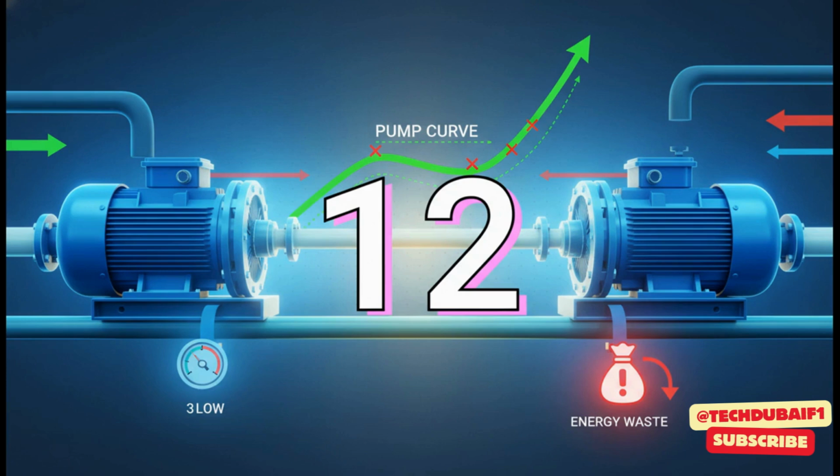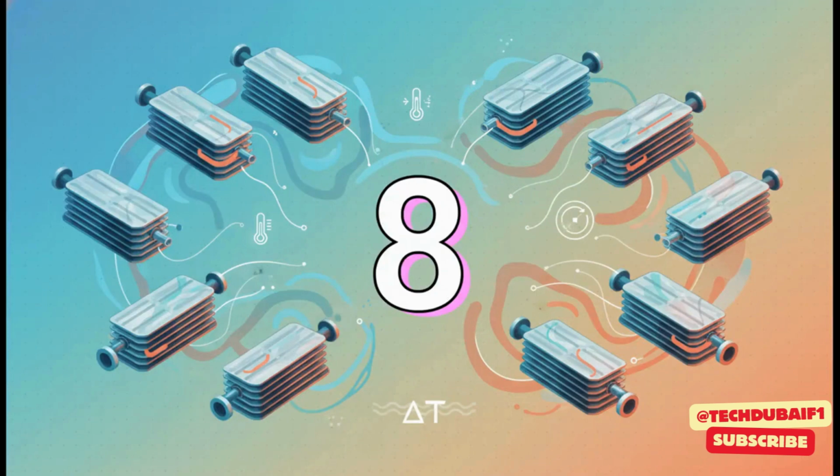That's basically their optimal performance line. Any little deviation from that curve is a major red flag for wasted energy. Next on the list are the 8 massive plate heat exchangers. These things are absolutely critical for actually transferring the cooling energy. The team goes over everything: flow rates, pressure, temperatures, to make sure they're pulling their weight. An inefficient heat exchanger can lead straight back to that low delta T problem we keep talking about.